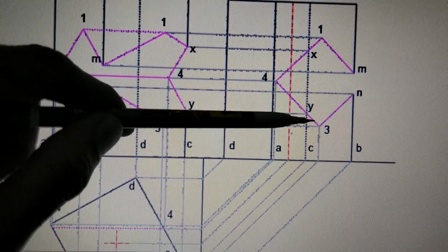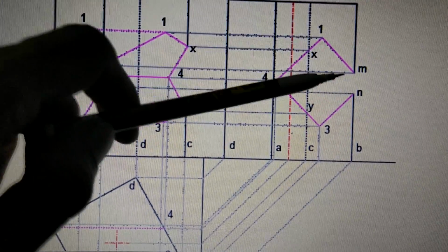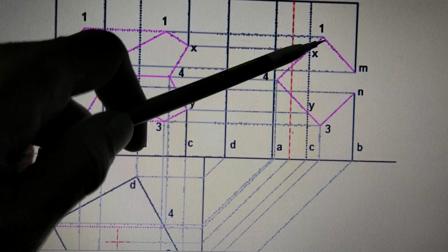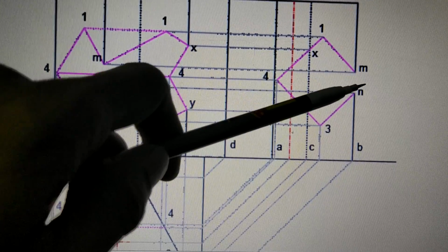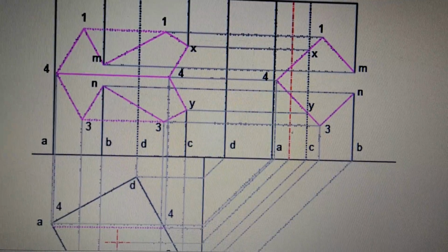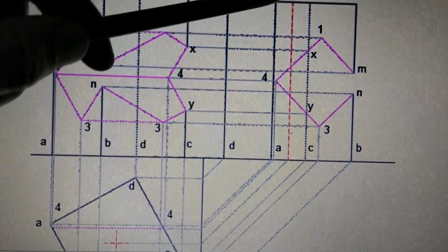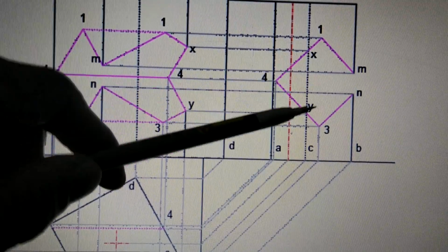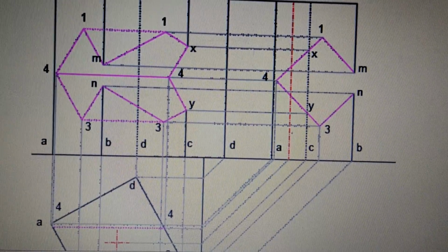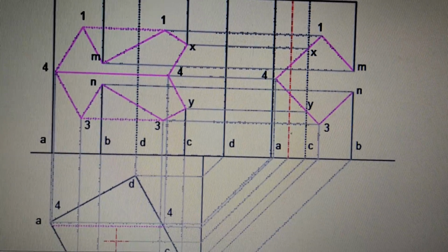Accordingly this is drawn, and after this is drawn, then we are going to draw this figure, and after we draw this hole, we are going to mark the points. So the corners we are going to mark 1, 3 and 4. Then this hole is intersecting the edge at B at M and N. It is also intersecting the edge at C at X and Y. So we have got 1, 3, 4, M, N, X, Y. These many points are there which we are going to plot. We are going to plot them one by one.